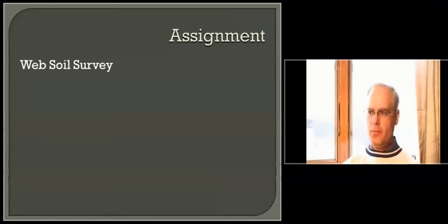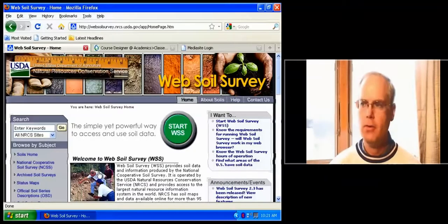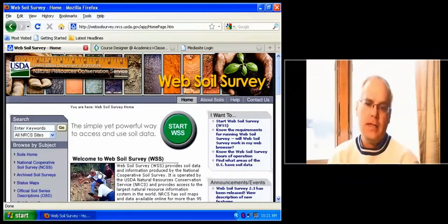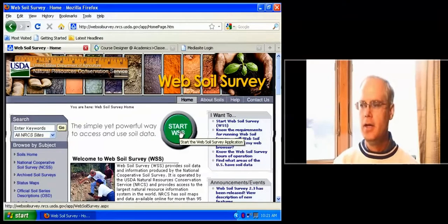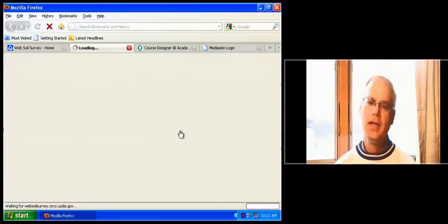Okay, this is the home page for web soil survey. You should be able to get at it with a link in the assignment, or like I said, the way I got it, I just type web soil survey in Google and it comes up usually on the top of the list. Now the first page is kind of a welcome page. It's got some instructions on it. You can work through that. To actually start it, you just need to click on the big green button there in the center and click Start Web Soil Survey, and that will bring it up for you.